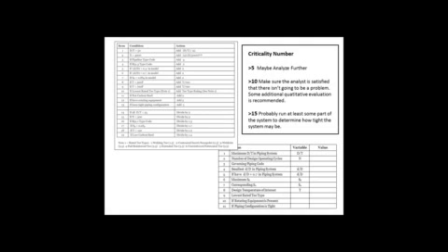So now if we go to the next slide, what we want to do is have a sense of when we need to take this more rigorous look. When do we need to go off onto the second branch? This is the slide that shows in the upper left-hand corner the criticality count. In the bottom right-hand corner are the numbers that go into the criticality count. And then when we make the criticality number determination, here's the criteria we want to use.